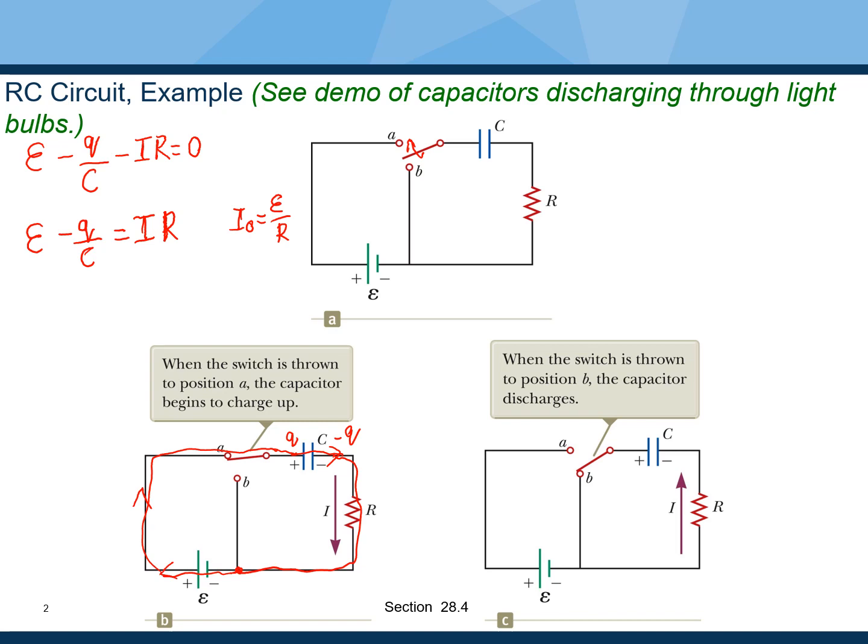So notice that initially, and I'll erase some of the things that we've drawn on this circuit just to make it more visible, what we have happening in this situation is that the amount of current flowing through the resistor is exactly equal to the amount of current that would have flowed through the resistor had the capacitor not even been present.